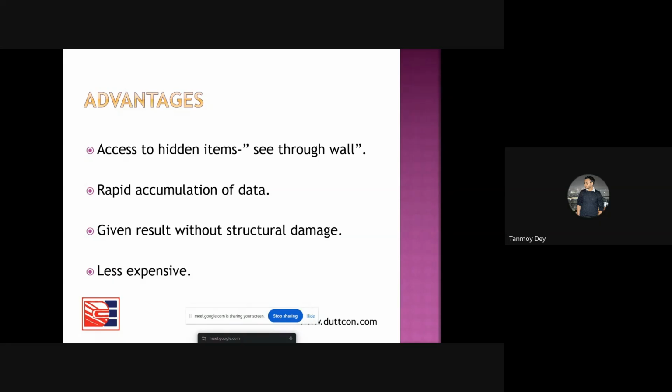Now, suppose we have some wall or structure; this kind of method, NDT, gives a full advantage. What advantage? The entire thing can be seen through, like a mirror. Everything inside is visible. Due to gross negligence during construction, sometimes instead of using 10 mm rod, the contractor may be using 8 mm rod. Sometimes they increase the spacing to reduce the cost and increase their profit.